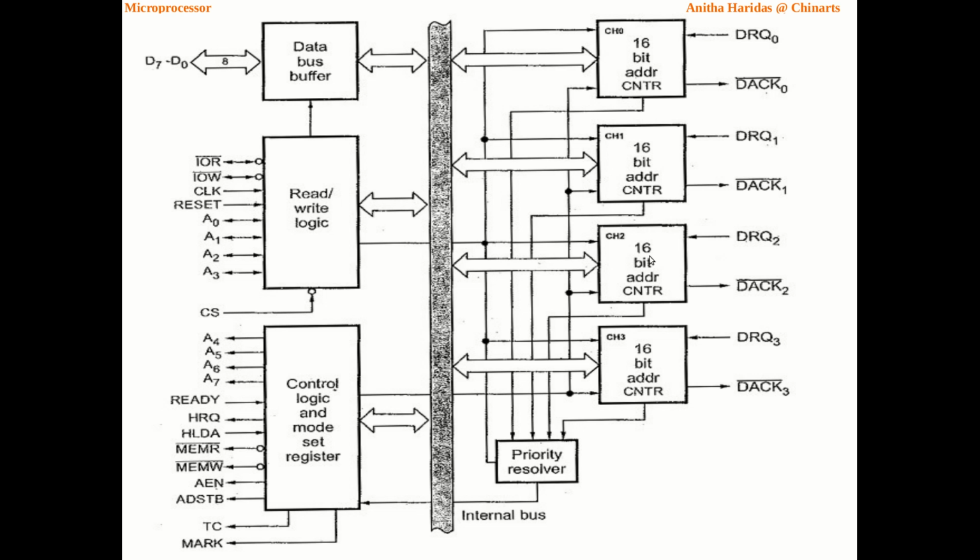Now how will it be receiving the data? If the line is having 0100, whatever data is coming in D0 to D7 will be moved to the lower significant byte of the address register in the first clock pulse. In the second clock pulse, the D0 to D7 values will be written to the most significant byte of the address register, because the address register has 2 bytes of 8 bits, the lower significant byte and the most significant byte.